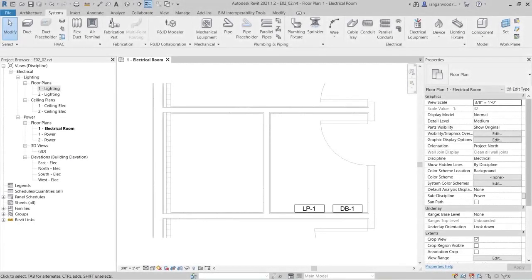Feed-through lugs for electrical equipment appeared in the 2020 release of Revit. It provides the option of connection between panel boards without the use of a breaker and can give a more accurate account of connections, loads and distribution within your project.